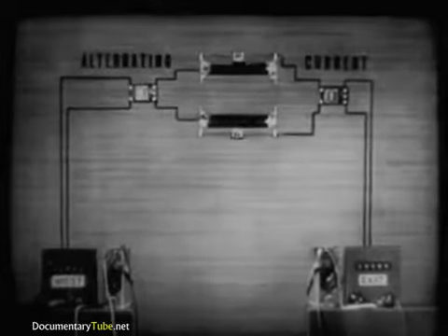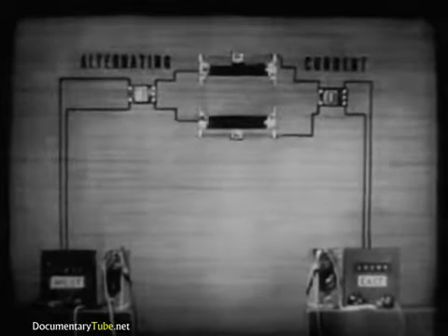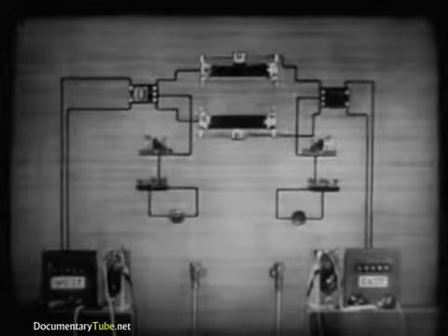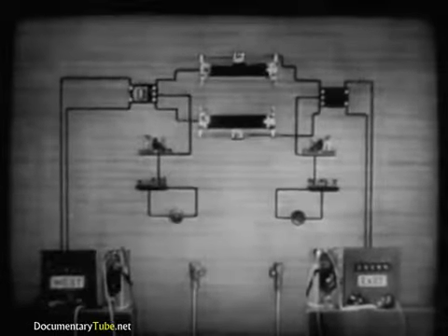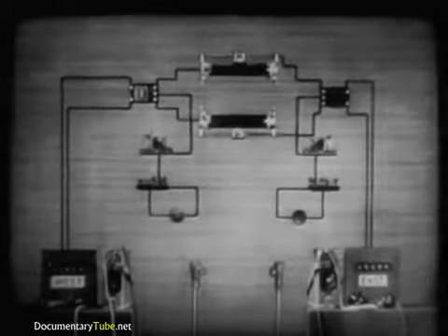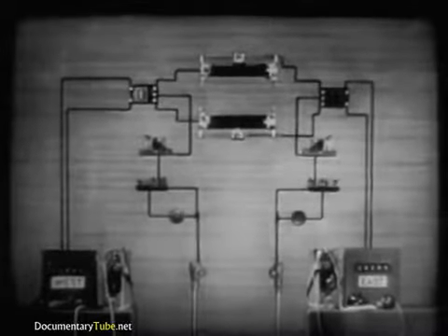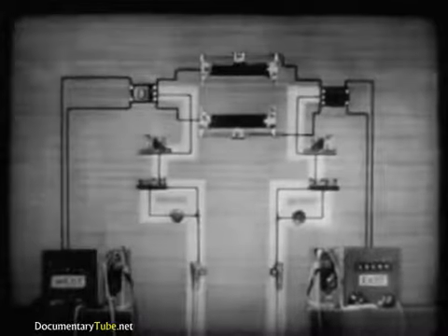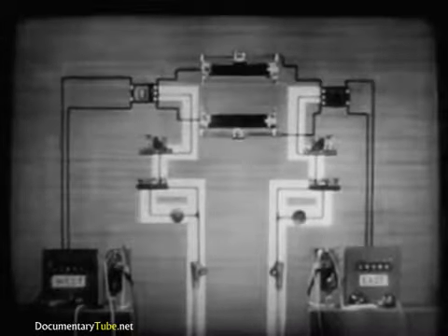We have seen that the coils repeat alternating or telephone current, so our telephone line is unaffected. Now we can connect a telegraph set to the midpoint of the line side winding of each repeating coil and complete the circuit through the earth. We have added the telegraph channel by using only a few extra feet of wire.